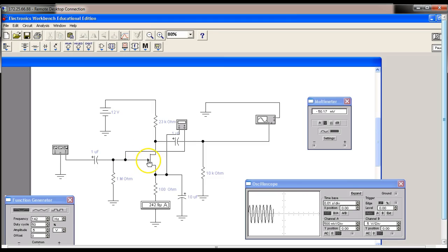So remember, this is P, this is N, this is an N channel. So when I put this in here, this becomes negative. So we're putting a negative on the P, and what does that do? Well, if I put a negative on the P, what it does is decrease the size of the channel, which causes the current to go down. And this is the way these things bias. So we call them self-biasing.